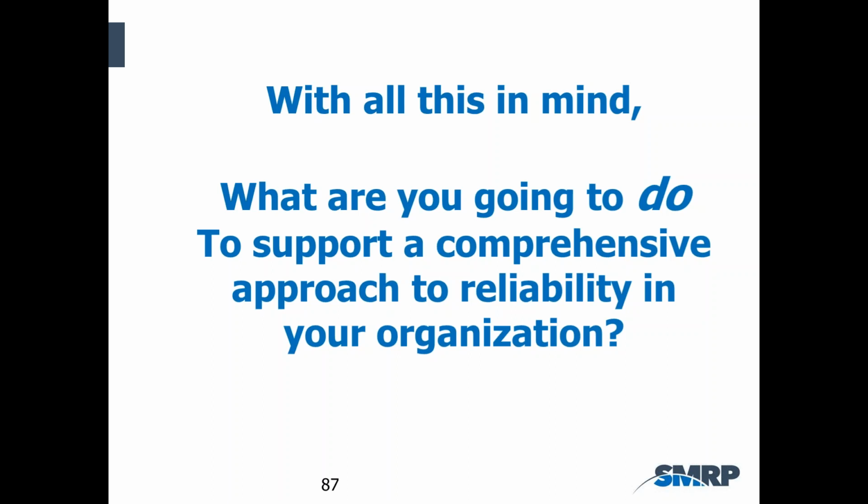And you ought to be monitoring something in the range of 70, 80, even 90% of the equipment using some sort of technique. It doesn't have to be predictive maintenance tools. In fact, most of it ought to be operators doing look, listen, feel, smell, process condition. And I count that as part of the condition monitoring program as well. So I don't know if I've answered the question, but that's my response to it.